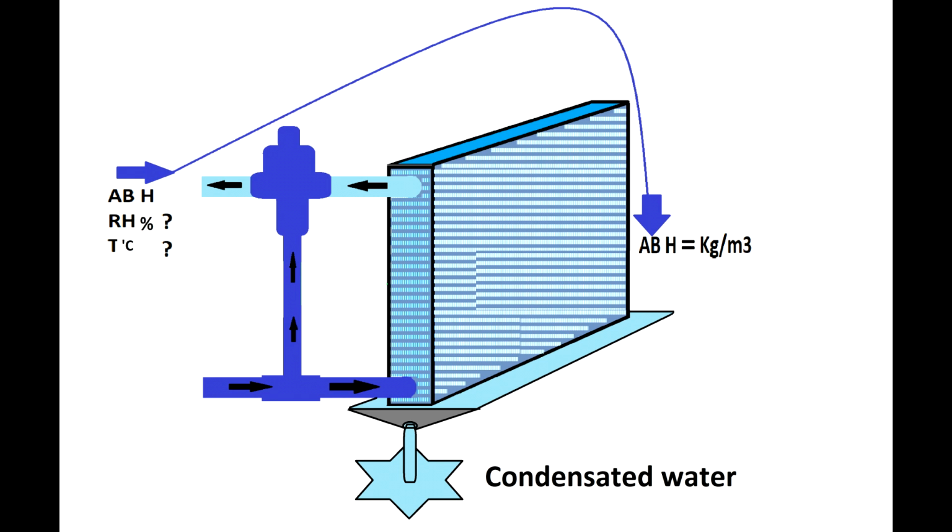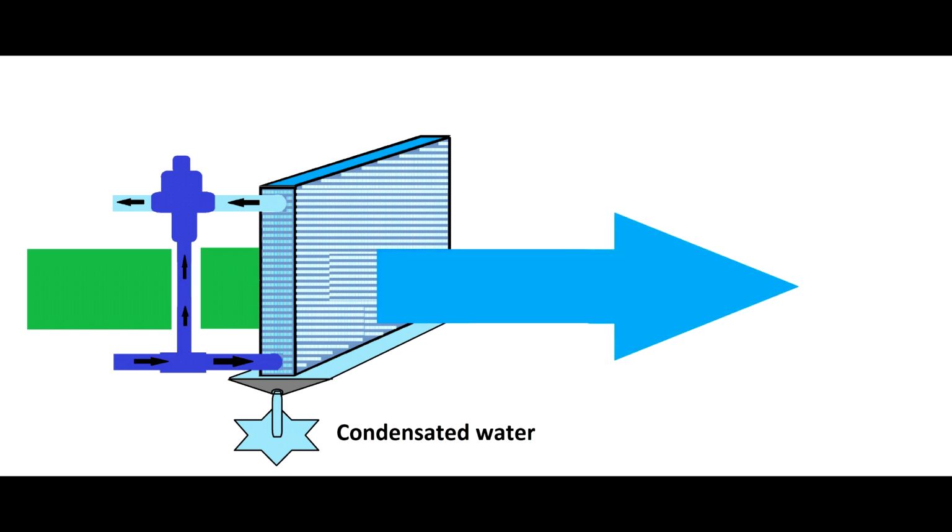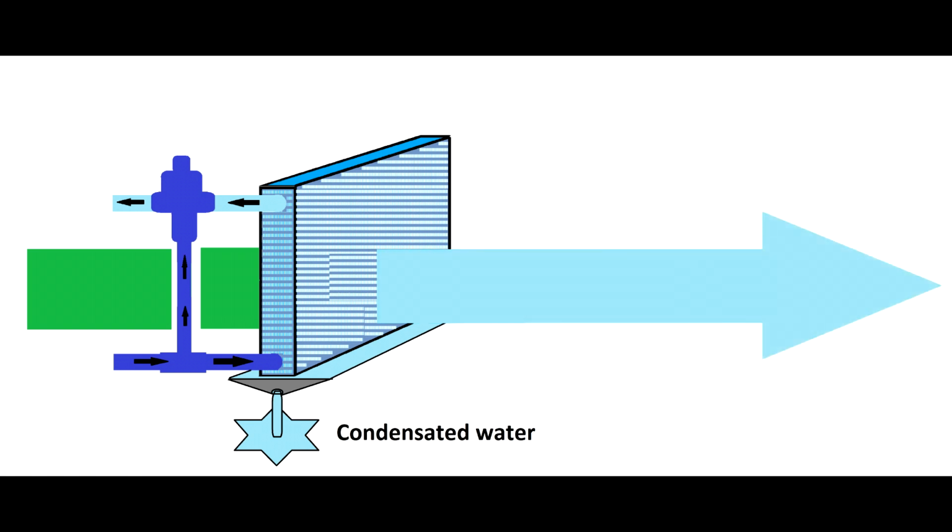The fan can push more air into the ducts, and that will not only affect the air change rates and the pressure, it will affect the cooling and heating capacity, or even the moisture removing capacity.